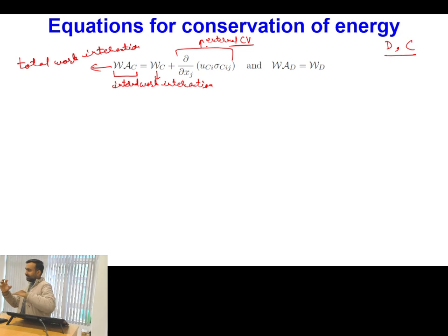If the particle is stationary or moving at slow velocity with reference to the continuous phase, then the continuous phase has to deviate around the particle and move across its sides. While the continuous phase is displacing around the particle, it is investing some amount of work, and that work investment is an additional investment only because of the presence of that solid particle. If that particle had not been there, that additional work would not have come. Is this point clear?